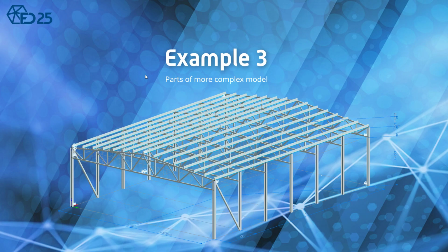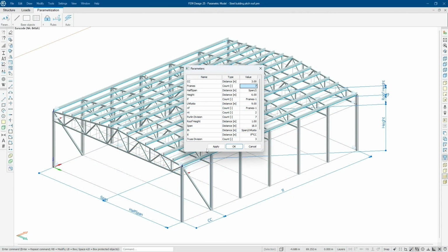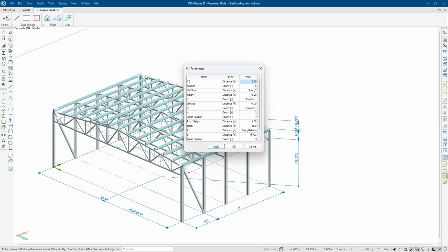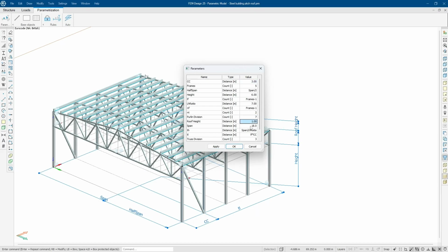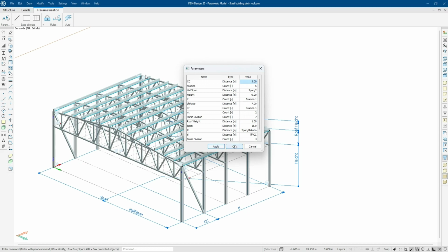And this is the final example. And if you now understand how you can overlap grids, this is super easy to do. So this is how it works. You can put the number of frames, the number of purlins as a different division, and what is the span to truss height ratio in your model, all the essential elements of your truss model. Let's go how this is done.